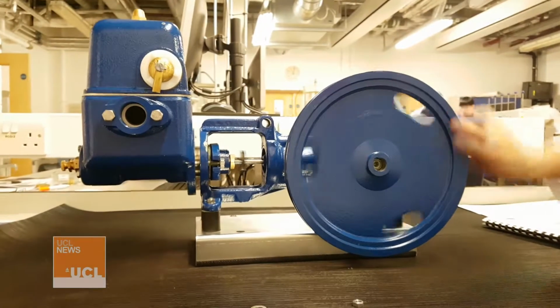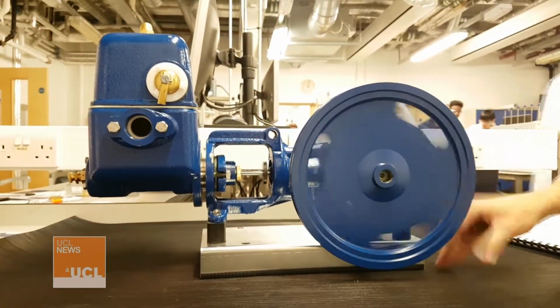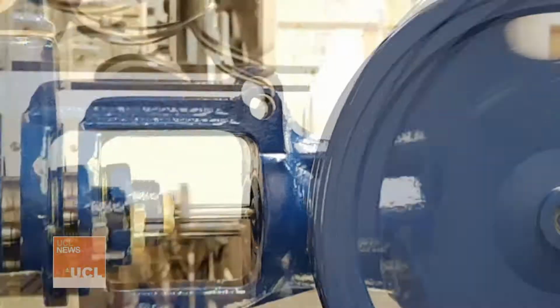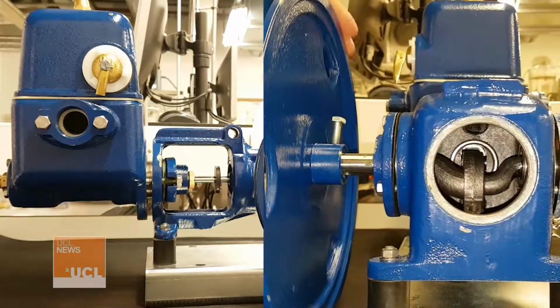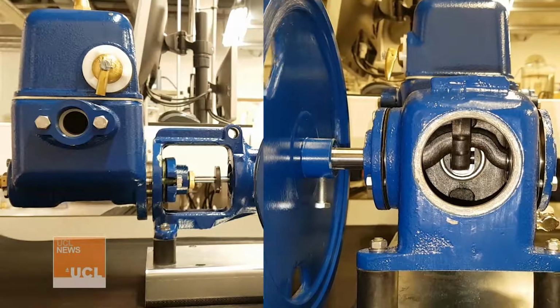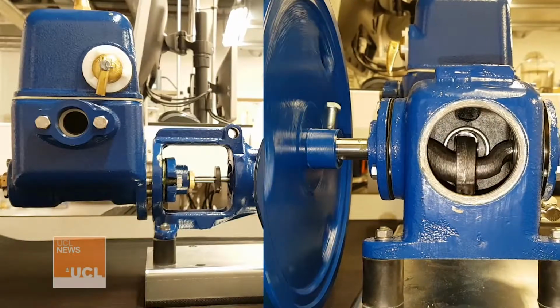It operates on a pressure difference created by the piston pump with two types of motion. Firstly, suction stroke, where the piston moves in a way which results in a larger pump cavity volume and lower pressure. As a result, there is a lower pressure on the suction valve, which allows liquid to flow in, and a higher pressure on the discharge valve that causes it to close.